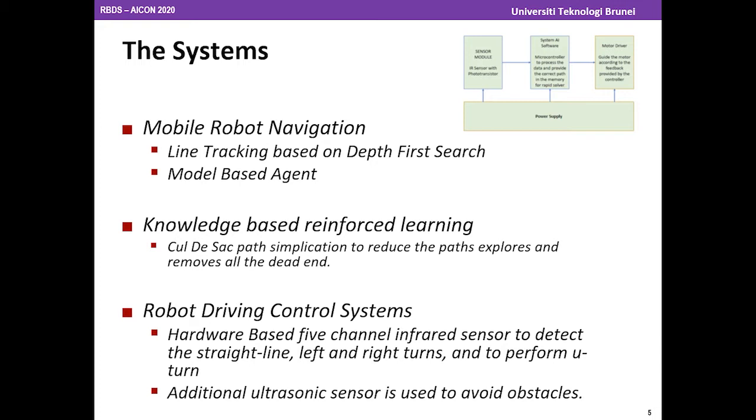And in the teaching phase, it uses the rule to navigate and traverse through all the paths, including the dead ends. And when you enter a dead end, you turn back or do a 180-degree turn, and then traverse the same path again. The turns are stored at the junctions, intersections, and then will be used by the robot for navigation after the path has been optimized, which is done in the second run.